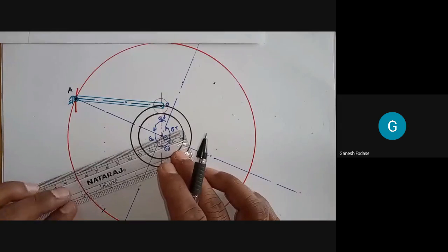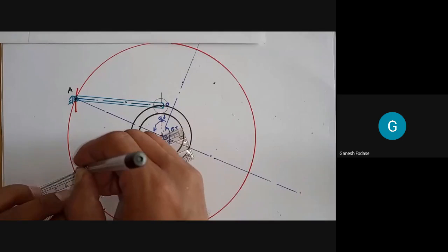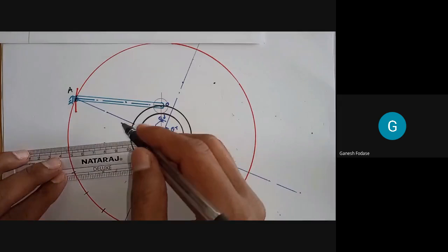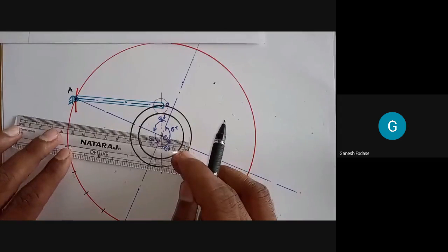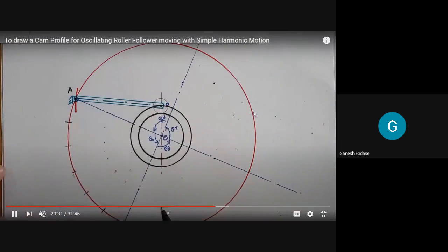See what we are doing basically, we are marking the divisions on fulcrum circle, and where we are drawing lines, we'll see later. First, see how we are joining it now. Whatever portion we divide, theta we divide into 6 parts. Just mark it on fulcrum circle. Now I hope you understand the red color circle is fulcrum circle. The radius of that circle is 8.4.